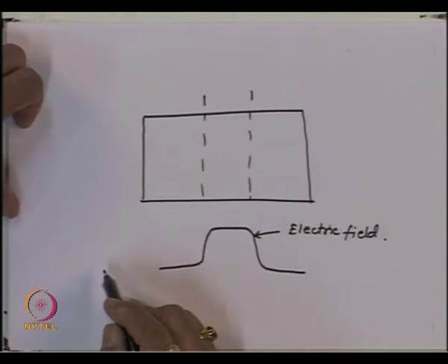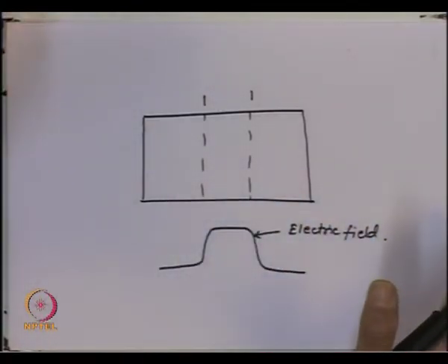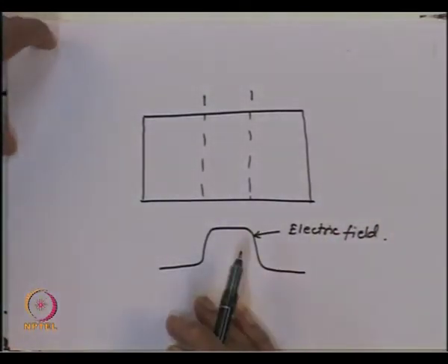What that means is that if you make a PN junction, then this length over which the electric field is present is much smaller compared to the length required for absorption of the photon or the characteristic absorption length of this material.